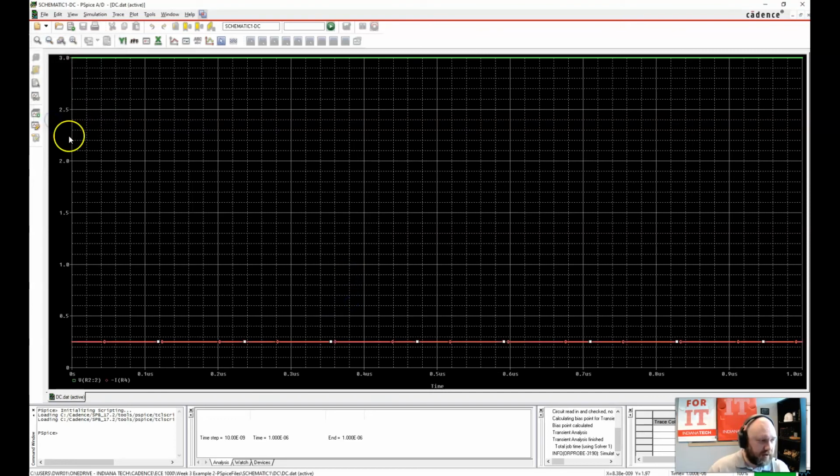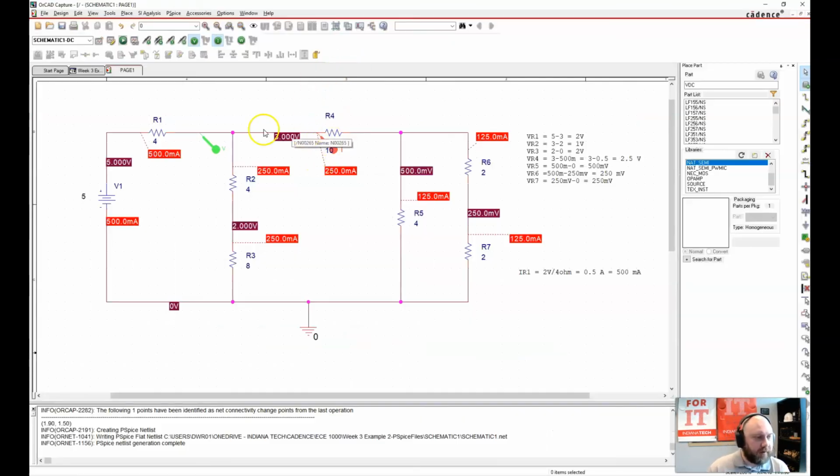Now, one thing that you have to be careful with is that sometimes it's not good to put both voltage and current on the same graph. The reason is that notice there's no units on this graph here, because it's basically saying, well, this line's at 3, and you just need to know that the green line is voltage, so it's 3 volts. And this line is at 0.25 or 250 milli, and you just need to know that it's current in amps. So typically it's not good to plot both of these on the same graph like I did. You either plot all your voltages on one graph and then all your currents on another, or something of that nature. But for demonstration purposes, I'm going to go ahead and put multiple measurements on there.